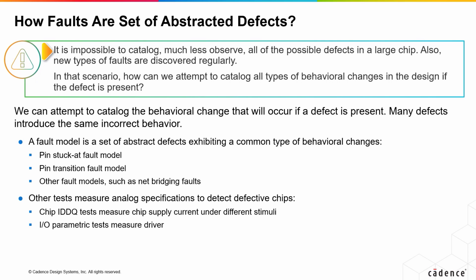The most commonly used fault model is the stuck-at model we have just illustrated. Based on many years of use, it does a very good job of detecting defects that cause static, non-time varying, incorrect behavior. This would include hard shorts and opens in the various metal traces, for instance. In recent years, newer technologies have been exhibiting time-varying behavior due to defects, and these behaviors are described by the transition fault model, which observes when a pin is too slow when it changes state. This will occur when a short or open is resistive rather than hard, for instance.